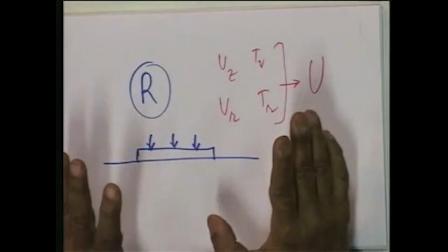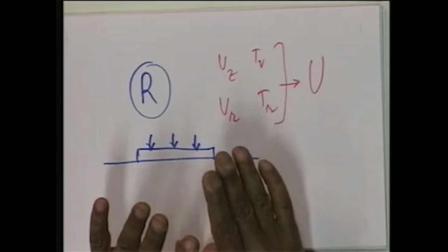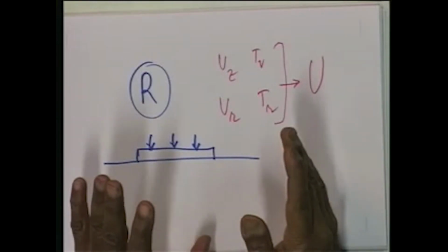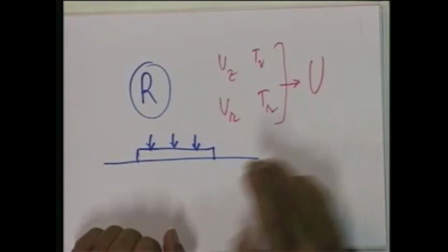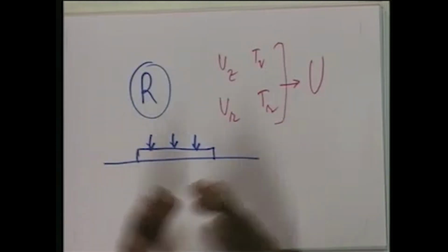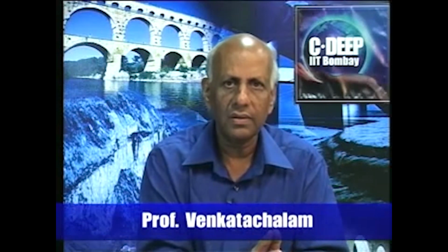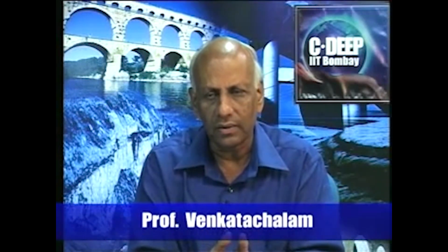And based on these two extremes, solutions have been evolved, on the basis of which we can calculate capital R for obtaining the value of Tr and Ur for radial consolidation. As in the case of vertical consolidation, this R is nothing but a length. It is the equivalent of the drainage path H, and therefore it is also a length, and this length will depend upon how these sand drains are arranged.